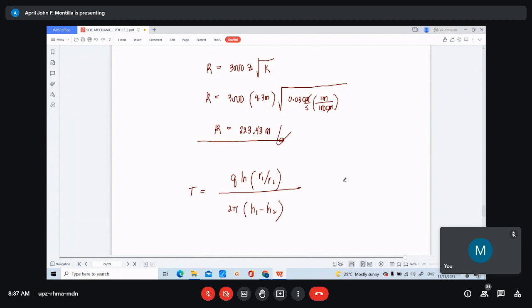Why? The transmissibility or transmissivity is the hydraulic conductivity multiplied by the thickness of the aquifer. That is our equation for that. Now, if the hydraulic conductivity has the thickness in it, you multiply by the thickness to compute the transmissibility, and it cancels. So that is our equation. Either of these two is okay to use for this kind of problem, or for this condition.